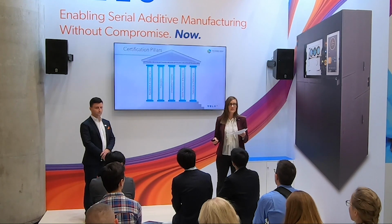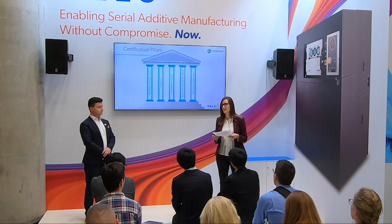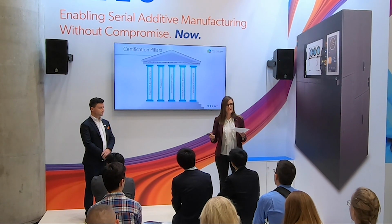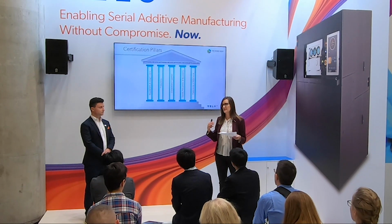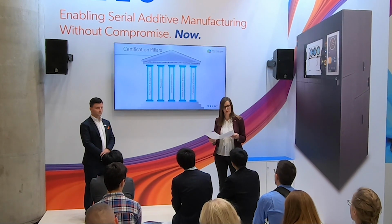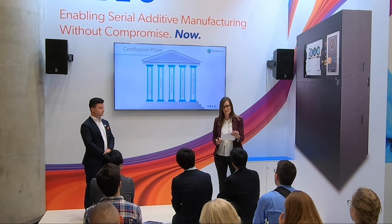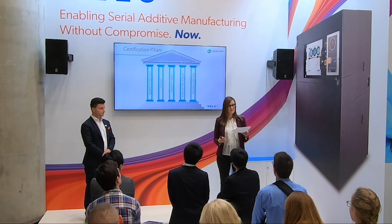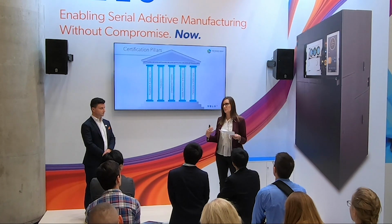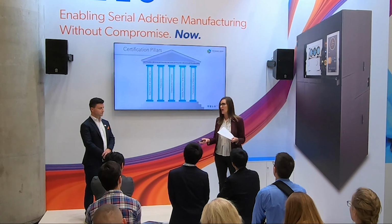Another definitely big area is characterized mechanical and physical properties. Obviously, we need to have databases and understand that. Due to the immaturity of the understanding of those relationships, we're still at a point of getting to have those large databases to base design on. The last one that once again is very closely related to the previous is predictability of performance. So this basically says whenever a designer calls out using an AM process, that they understand and can be assured that they're going to get the properties required for performance of that part. So classic would be, in metals would be MMPDS, S basis, A basis, B basis allowables.